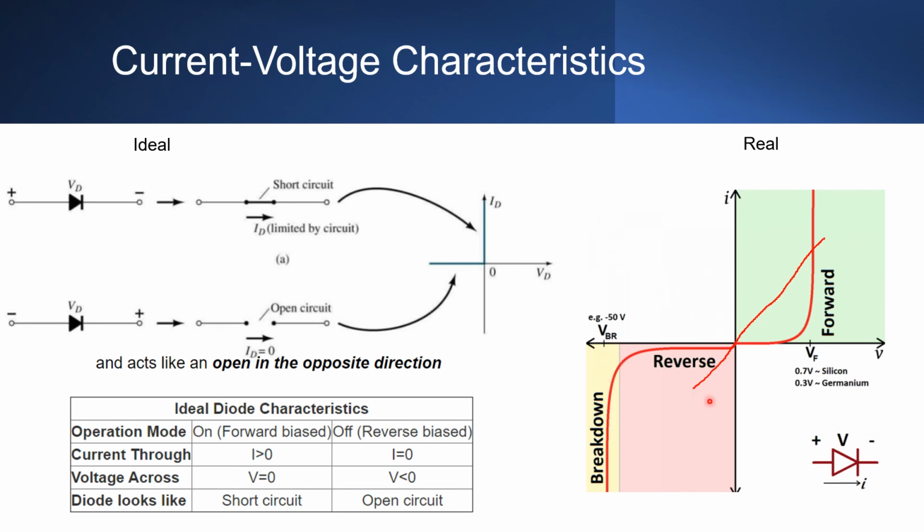So depending on the voltage applied across it, a diode will operate in one of three regions. First is the forward bias. Here, when the voltage across the diode is positive, the diode is on, and current can run through. The voltage should be greater than the forward voltage, about 0.7 V, in order for the current to be anything significant. Forward voltage might also be called either the cut-in voltage or on voltage.